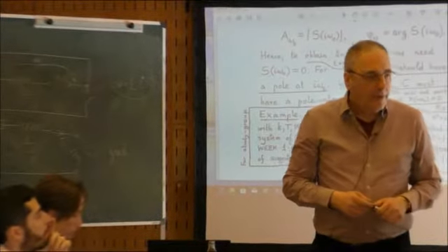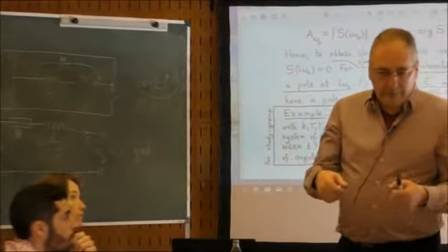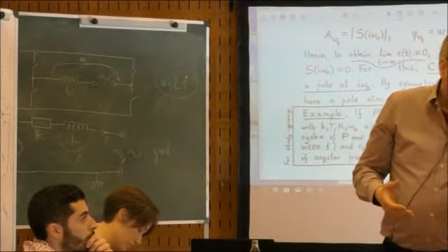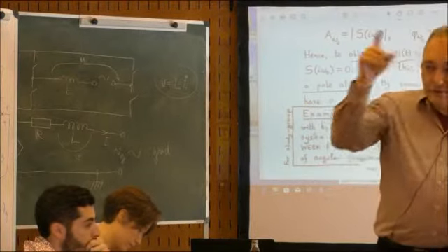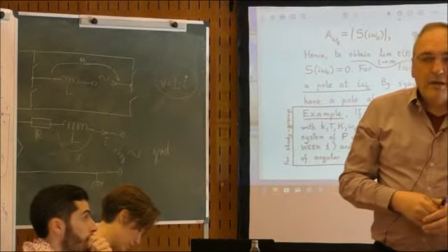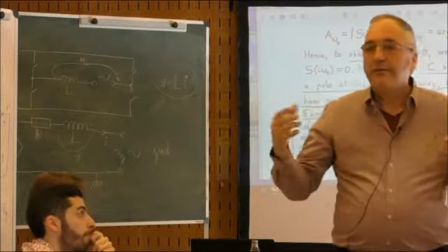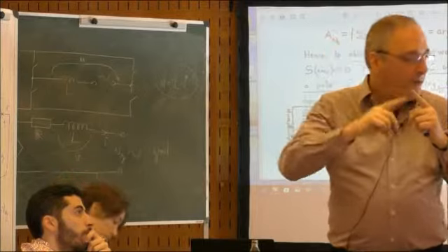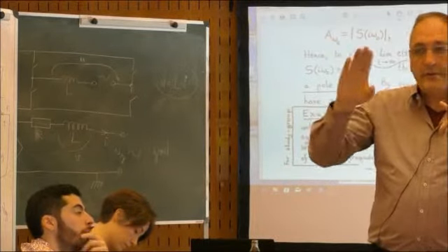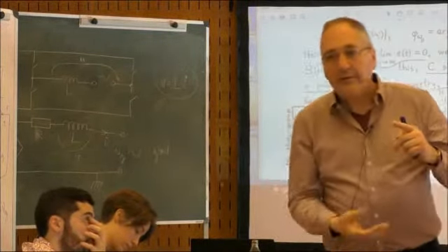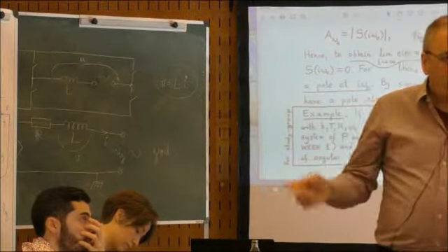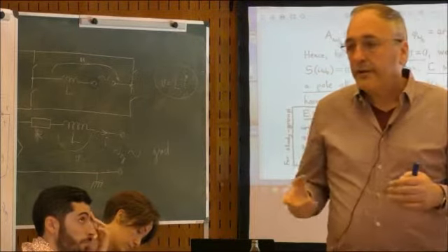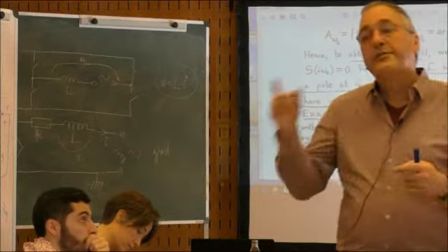If you drill a hole, for example you drill a tunnel, then you have a rotating drill, and depending on the structure of the stones where you are drilling, at certain angles you have big resistance because you have to cut some hard stone, and at other angles the resistance is smaller. So you have a certain periodic pattern for the load torque of this drill.